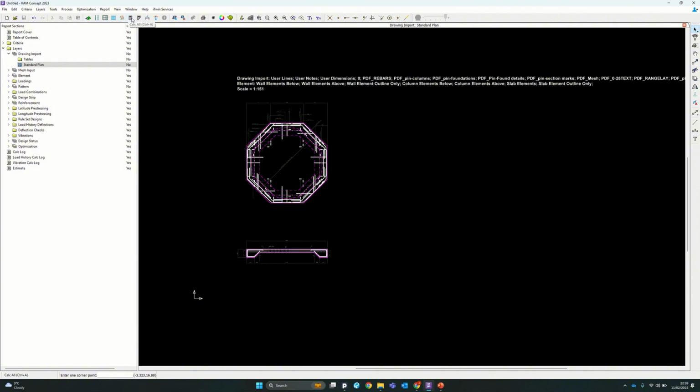Polylines. These two are very useful, well, necessary: Calc All and Partial Calc. Partial Calc is there if you want to save time. It will only do a certain amount of the process. But as you get further down the line, if you've filled all your load cases in, you've modelled your objects in correctly, and you've done the design strip stage, once you press one of these options, it will go through and analyse everything. I'm not too sure about either one of these all that much, but then again, these three are what I use most as well.